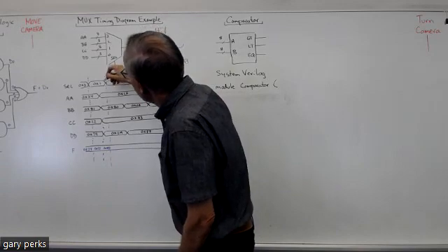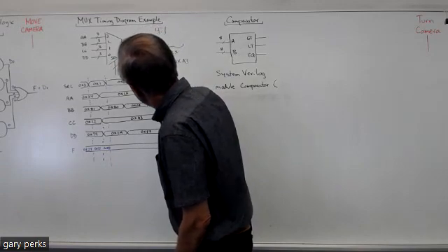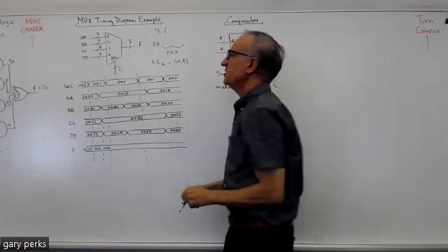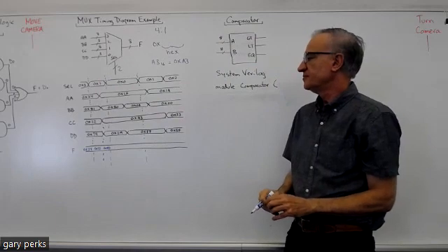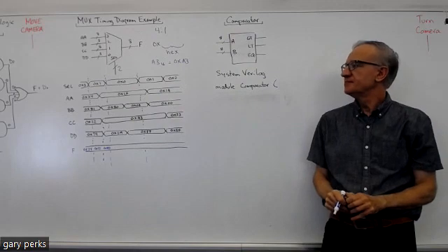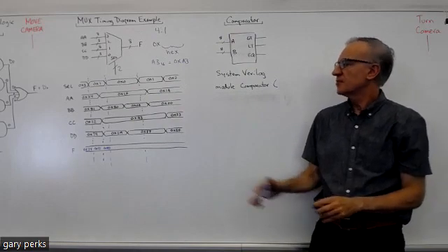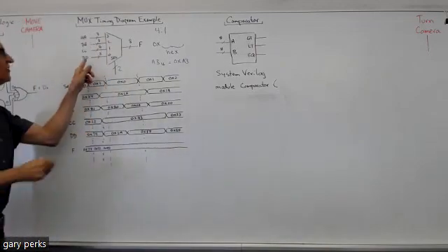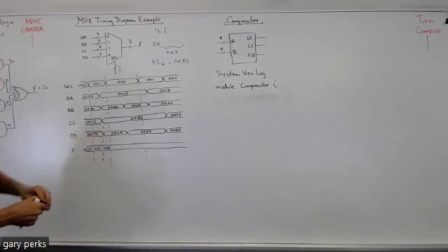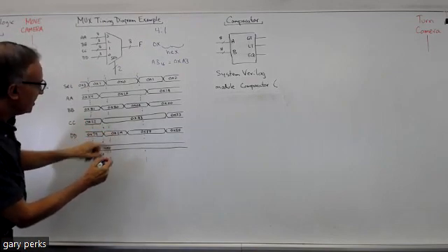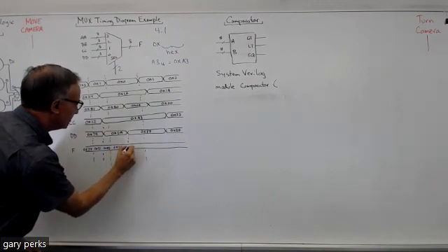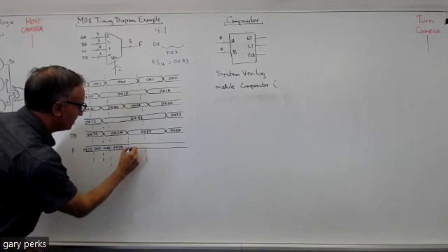Yeah, let's do one more. Now it changes the select from a 1 to a 0. It's going to be 0x29 and then 0xFF, because when the select is 0, the data on input 0 gets connected to the output. So you look at DD, and during this time it's 2A hex, and then here it's going to change to FF.